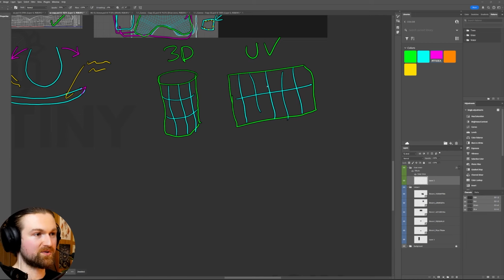Now in a perfect world, when we have done the unwraps, we would be able to make adjustments to this. For example, bring out extrusions and then it will auto unwrap. But unfortunately that doesn't work. So as to your question, when can you actually edit the 3D and keep our UVs? It's primarily when you're inserting edge loops. So the geometry is somewhat changing, but the overall structure and the silhouettes aren't.